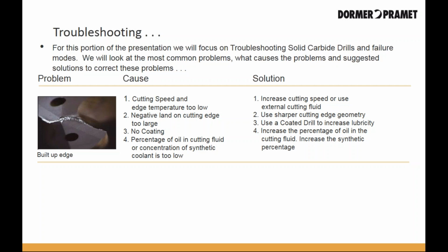And the solutions for this can be to increase your cutting speed or use external cutting fluid. Use sharper cutting edge geometry. Use a coated drill to increase the lubricity and increase the percentage of oil in the cutting fluid or increase the synthetic percentage.